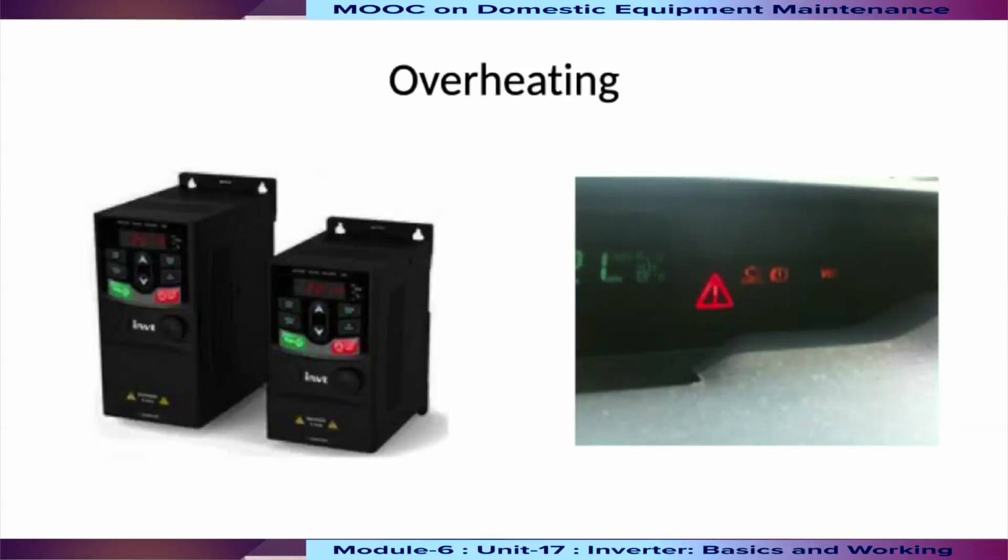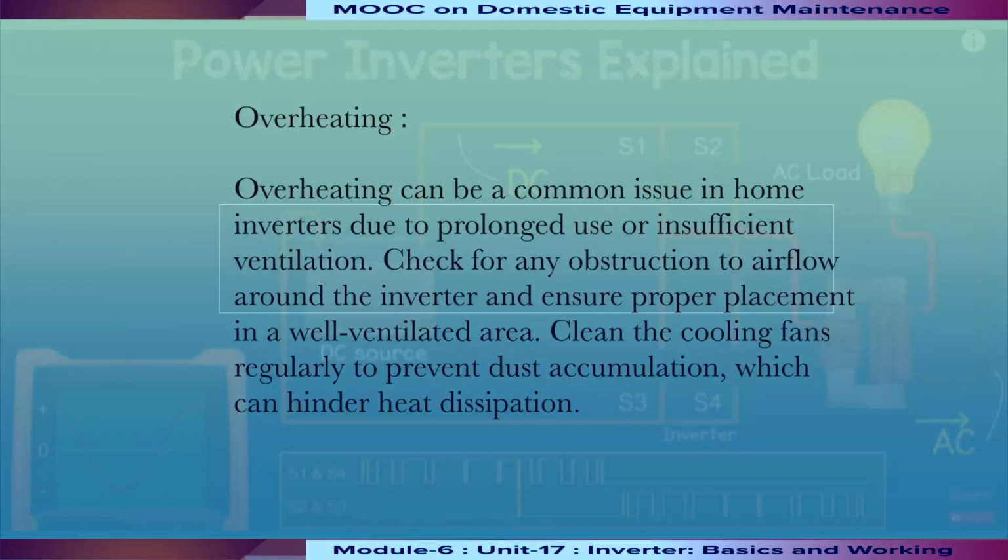Overheating. Overheating can be a common issue in home inverters due to prolonged use or insufficient ventilation. Check for any obstruction to airflow around the inverter and ensure proper placement in a well-ventilated area. Clean the cooling fans regularly to prevent dust accumulation, which can hinder heat dissipation.